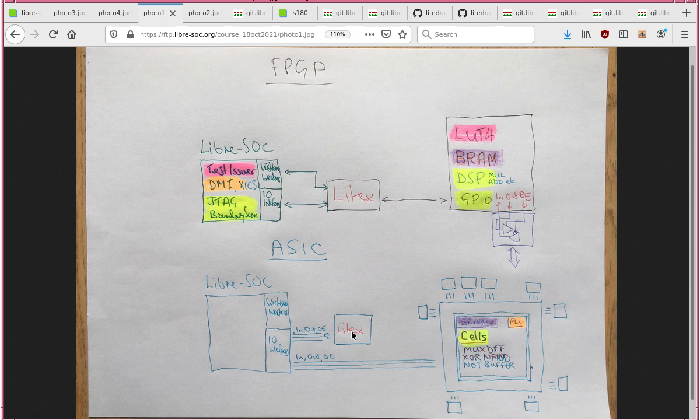In addition to that, we had to define a platform which had its own PLL, but as a black box cell. And likewise the SRAM. So in LiteX, if you have a look at the platform, the LiteX platform code defines and understands the PLL block and wires it up for you, so that when the bitstream is programmed, it will enable and connect everything up.